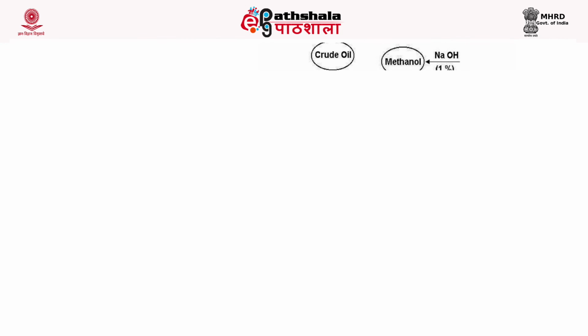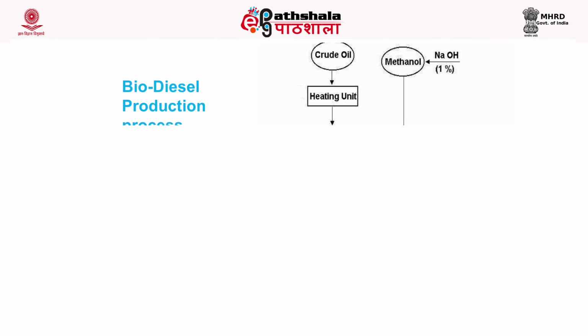This is again a batch type, very simple process, which was developed at Punjab Agricultural University, Ludhiana. Here the crude oil is heated to a temperature of 60 degrees Celsius, and in a separate chamber methanol is mixed with 1% sodium hydroxide and heated, and then both the crude oil and methanol are mixed together in a mixing tank and then allowed to settle for 4 to 6 hours.